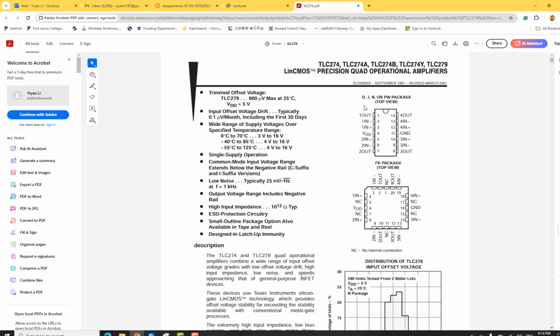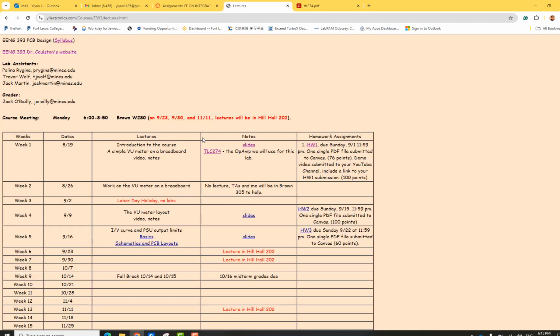But if you give it feedback, are you still having that infinite open loop gain? You still have it across the terminals, but the input and output will be changed. You are having a finite closed loop gain determined by the resistor ratios. And so this time, we are using this op-amp as a comparator.